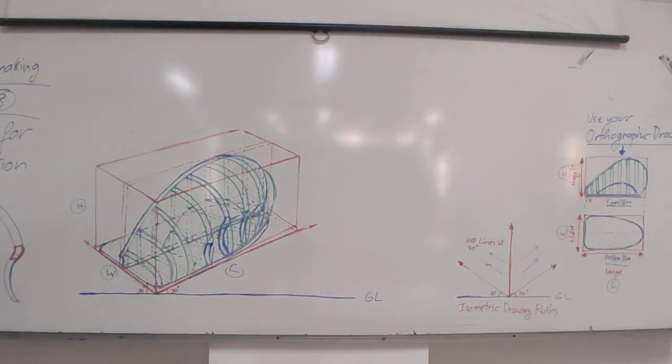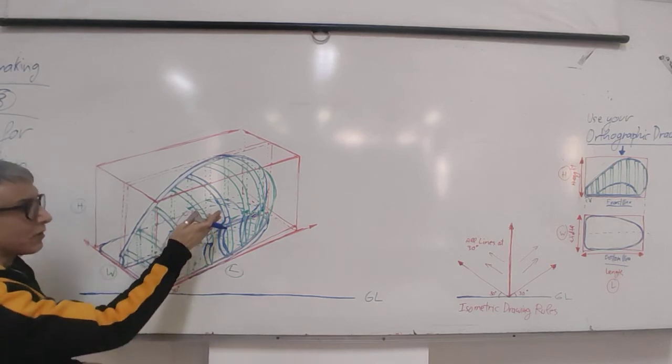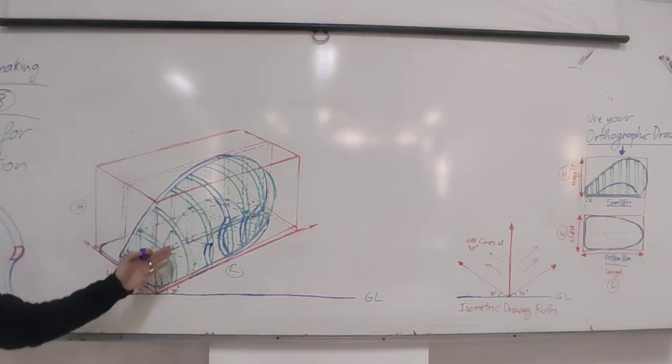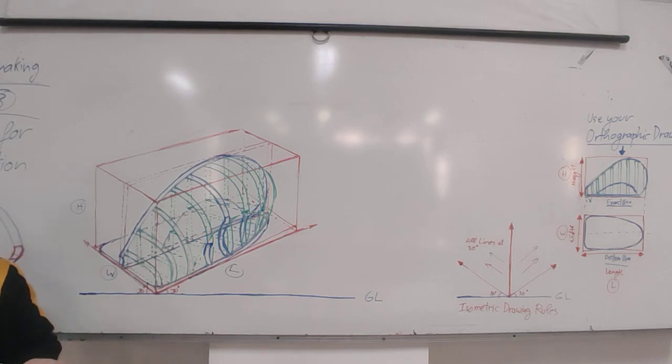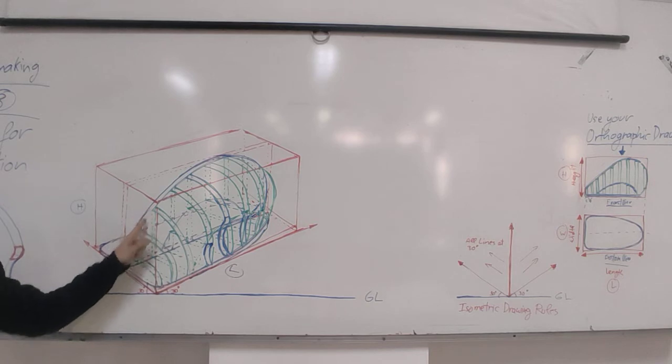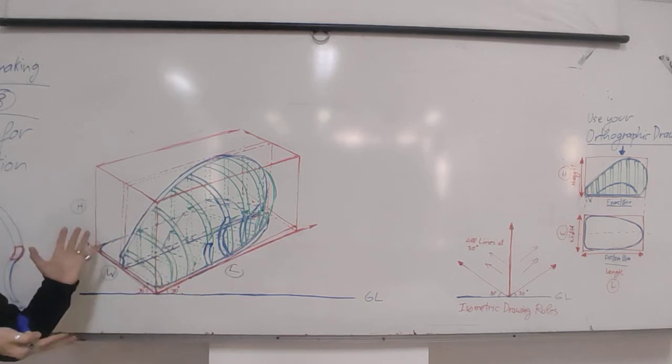Okay, so this should be the thickness, always 2 millimeters, okay? 2 millimeters. Don't forget, everywhere where I measure should be 2 millimeters. And you start making this modification, so as you can see, you have a lot of lines now, okay? So be careful to keep the dotted lines dotted so we can differentiate them from the object lines.